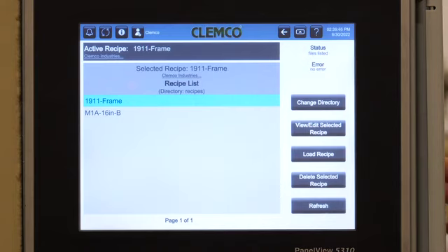It may require a larger memory PLC to do all that logic, but the SD card can hold as many as we want, and as long as we're planful about when the company wants to buy a new machine from us, and they tell us we're going to do 250 recipes, we'll buy the right size hardware components to make sure that's available. But the system functionality is already there. It is able to do greater than 500. Okay. So that's more than any company would probably ever need.